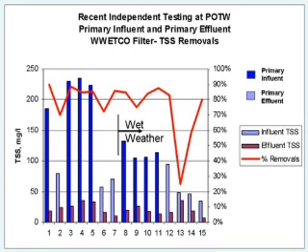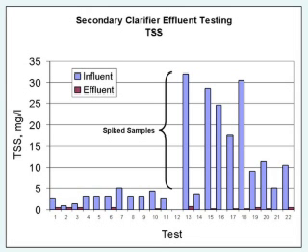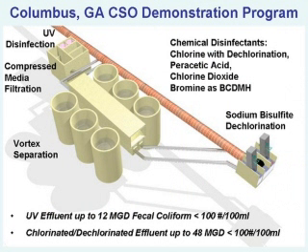So using the technology in multiple locations can sometimes do more things for you at the wastewater treatment plant than just treating the wet weather flow path. So the engineers looking at these opportunities would be well suited to provide greater pollutant removals. This is just a picture of the compressed media filter similar to what was put into Columbus. It has been tested at different facilities for CSO treating, CSO flows. These are full-scale pilot facilities for the compressed media filter, and it has been looked at for SSO treatment, primary influent treatment, primary effluent, and as a tertiary filter itself.